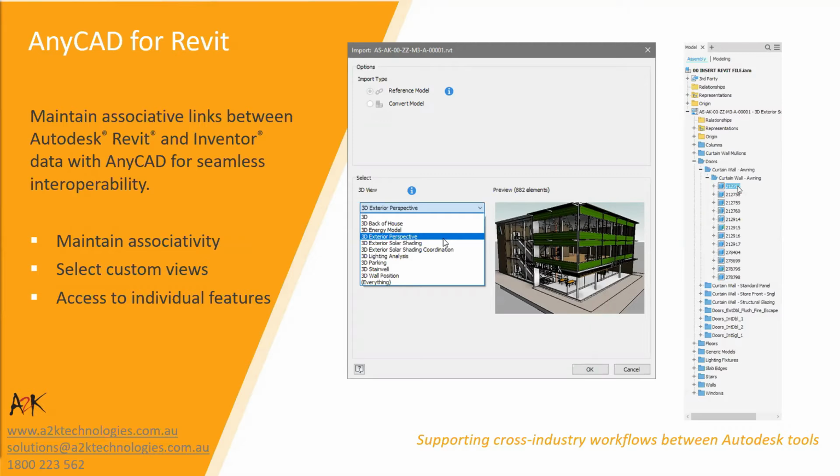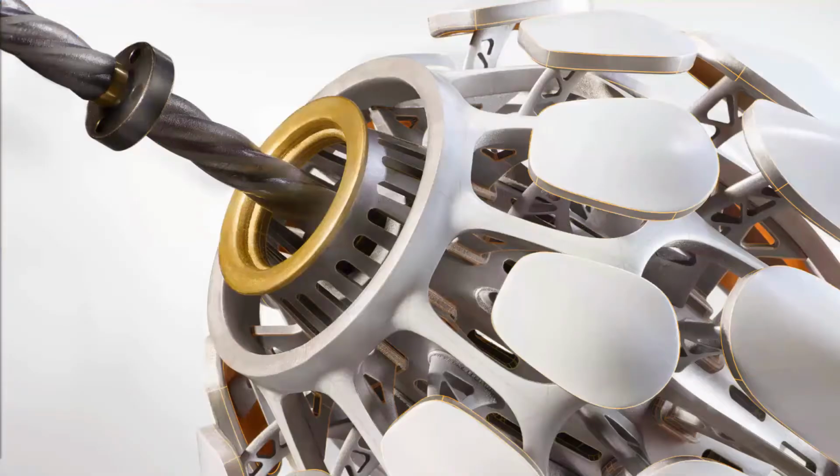That Revit project can be accessed from a local file or coordinated via the cloud using Autodesk BIM 360's CDE, or Common Data Environment. Changes during the design process are inevitable, as we all know. Now, when the Revit model changes, we'll need to update the Inventor model to match. Now, because the Revit model is referenced into your Inventor assembly, without file translation, any changes to the Revit project will automatically be updated inside the Inventor assembly. Let's take a little look at that.